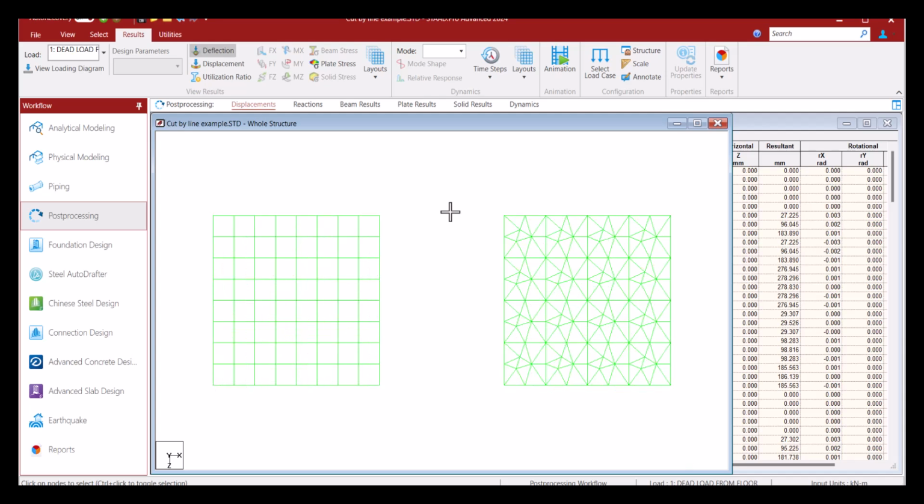Let's switch this off. Okay, now here you can see I have these two. Now if I am being told, okay, I want to design the reinforcement considering that my moment direction would be like this. You can see my cursor. If it would have been bent about this axis, I want to design the reinforcement against this. You can find that. Okay. All you need to do, all the local axis moments should be resolved along these directions.